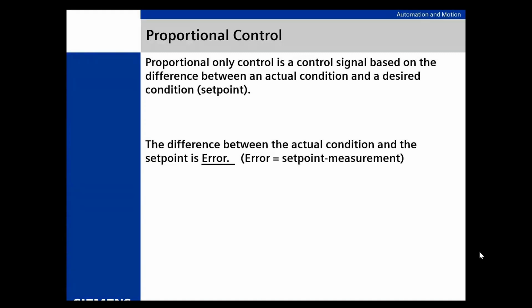Now, it's not the best control, but think about it this way. If you came to me and said, Wes, by God, I want my air conditioner to keep my house 72 degrees, right on 72, okay, I put a PID controller in there and your air conditioner is going to go on, off, on, off, on, off, and self-destruct.